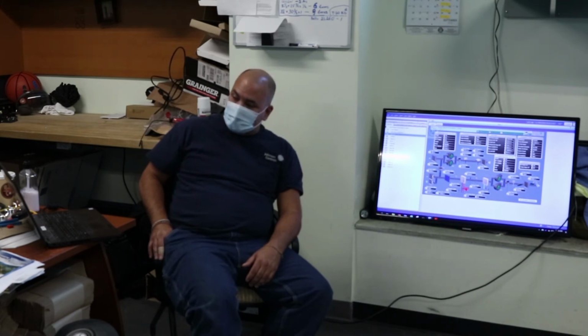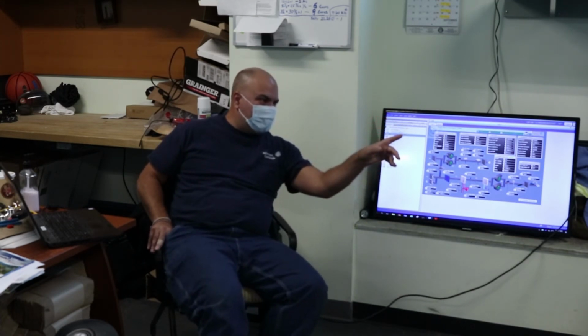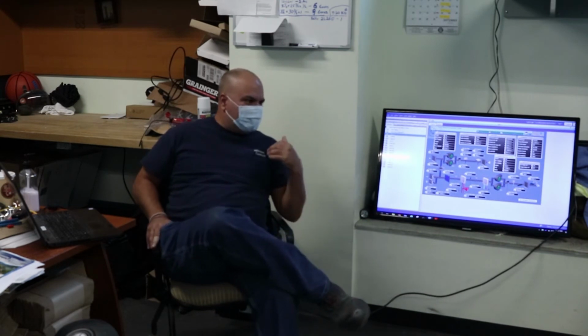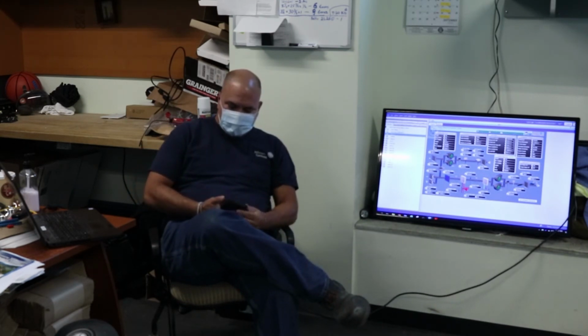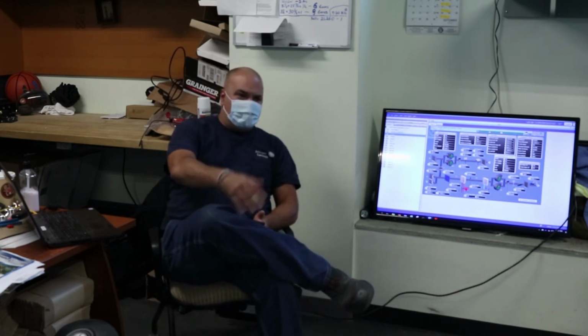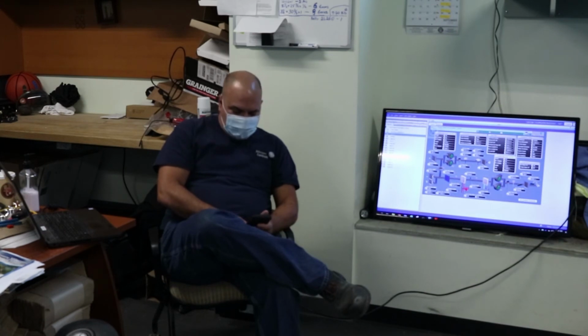We had a problem, which I think they're still trying to resolve, where we found the MAUs running and the outdoor air dampers overlapped. So of course the MAUs are trying to make static pressure and the outdoor air dampers are on. So you had two of them running balls to the wall. I think that was recently, like last week or something like that. No, it's been caught more than once. We tested it a week or two ago, and I think something got left in an override during the test. It was in the spring that I found this happening, the first time I actually caught it. April, May, when I first saw it and reported it.